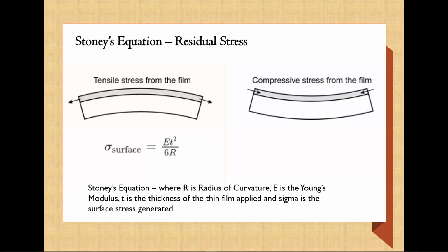And wafer curvature, as shown here up at the top, is the most common technique to determine the intrinsic stress effects brought into the material by the PVD thin film coating. And the goal here being to measure the curvature of the film with respect to its thickness.